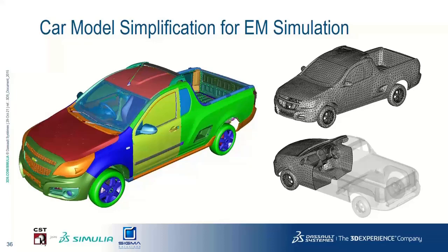So this can also help you to really break down the simulation time. And you see on the right the gray materials. So I think they used ideal PEC as the material, again, just to get an initial simulation done, which also runs much faster than if you're using lossy material.